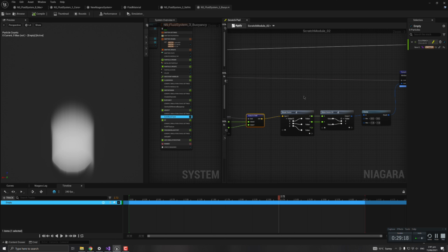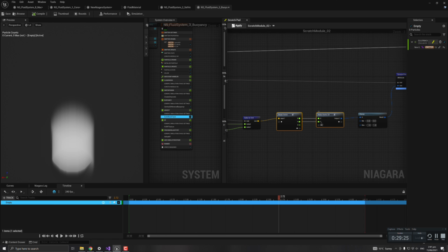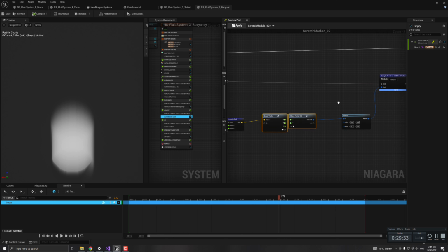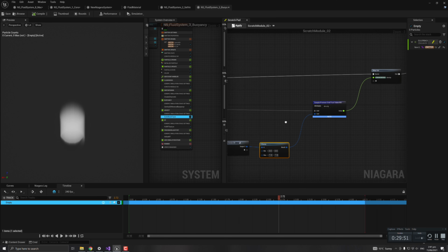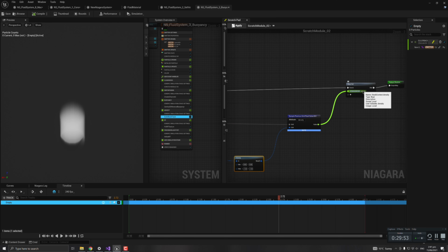And then we want a 2D vector, but this node outputs a 3D vector, so we have to use these two to split and then re-output a 2D vector. And this is probably where it's worth adding a 3D to 2D cast here or something, or a little function helper, which might be useful. And then I want to clamp, because if the velocities are outside of the current grid bounds, then I don't want to sample it out into nowhere. I want to limit that to the actual bounds of the grid itself. And then we sample the density and write back.